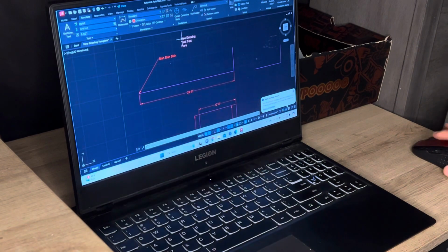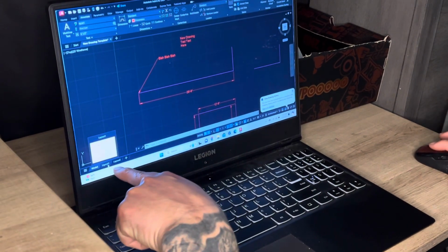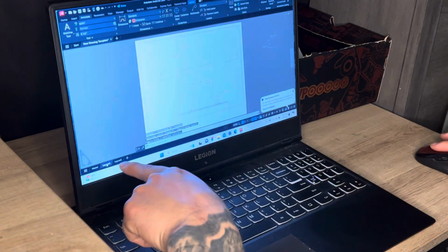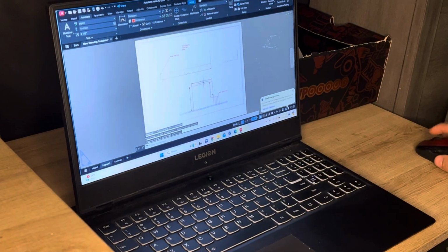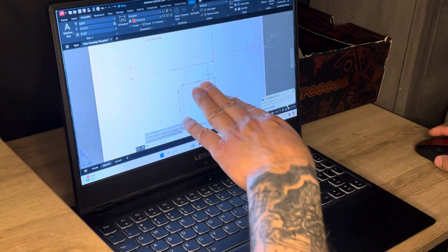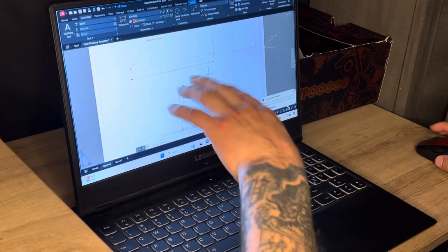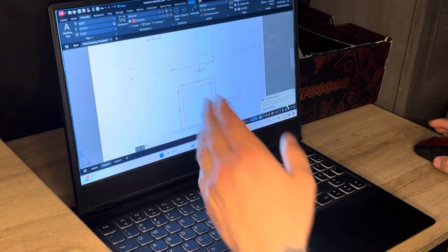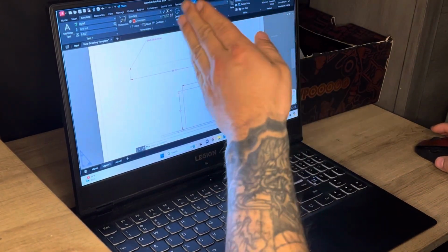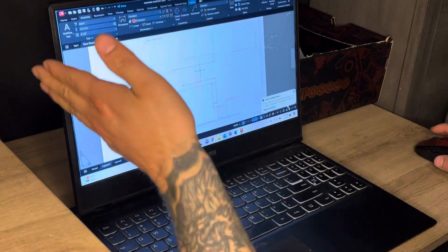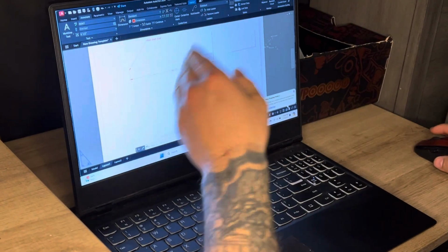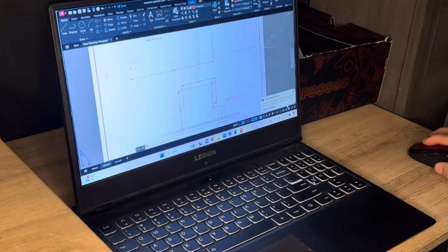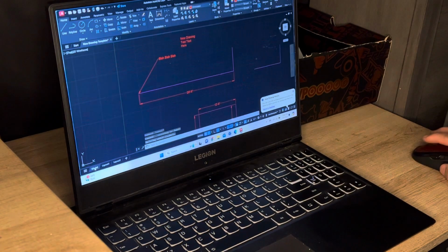If I go to paper space, which is my layout down here, I got different tabs, and I could do different layouts off the same drawing, but that's right here. So I could read it good enough for now, but maybe I change it a little bit to make it more legible when I turn in my drawings. And if I change one, I'll go through at the same exact time and I'll change all of them, so that way I'm not having any problems. I'll make one look good, change them all. Okay. I'll go back over here.